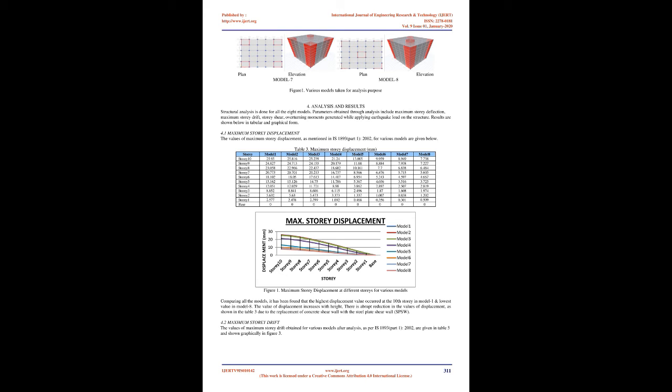6. Selection of beam and column section from toolbar. Draw the building frame section. Quick draw beam properties of beam section. Select beam properties. Draw the beam. Quick draw column properties of column section. Select column properties. Draw the column. Quick draw slab properties of slab. Select the slab properties. Draw the slab.